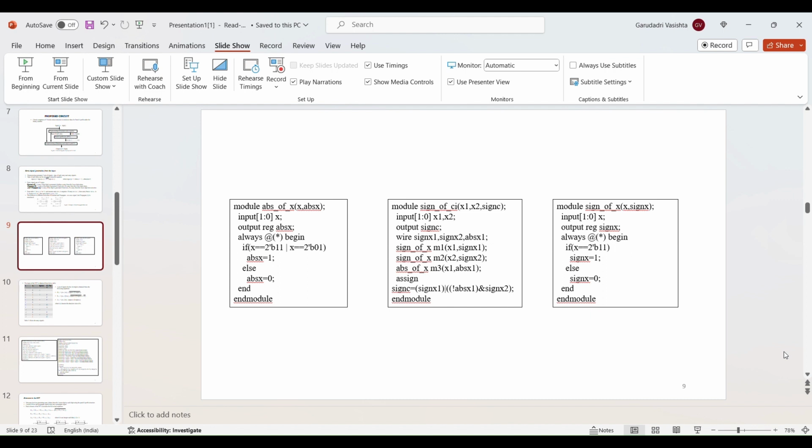Now I am going to explain the next module, which is PPT, which means parallel prefix tree. As Shivam has explained, what we have calculated up to now is the carry signals of each and every digit. Now we are going to calculate the carry chains from the lower digit to each and every digit, which can be represented by G of i comma j, P of i comma j, and A of i comma j.